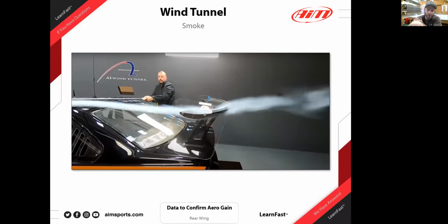But yeah, you can see the little gurney flap on that wing. Yeah. And that was a funny example of, we've done a 1/2-inch gurney flap on several wings now. That particular wing we're looking at now had the biggest downforce gain from a gurney, which is kind of interesting if you think, how does a 1/2-inch gurney make anywhere from about 40 pounds? That particular one was like 100 pounds of downforce.